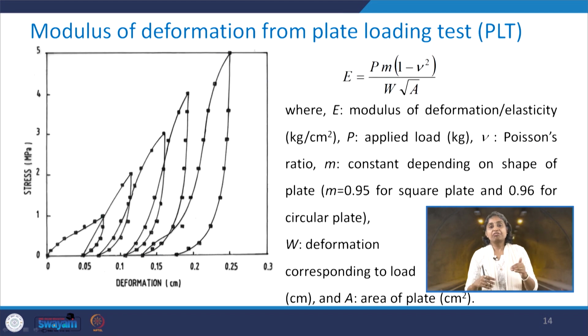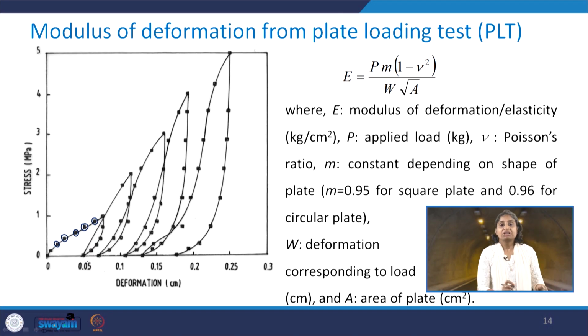So what we do is apply the load, then wait for some time for the deformation to take place, then we remove the load in stages. It is exactly the same as you conduct a cyclic plate load test in the case of soils. You see various points that tell you this was the load increment and the corresponding deformation, and while unloading also it is done in steps, not that the whole load is removed immediately. So first cycle unloading, then again it is loaded, unloaded, and a similar thing is done.